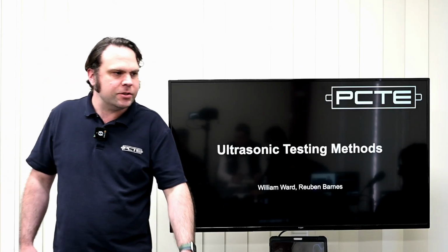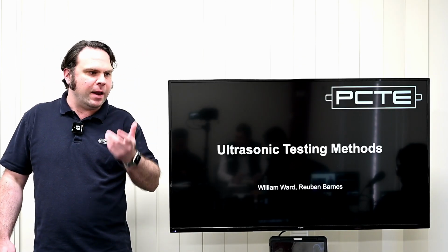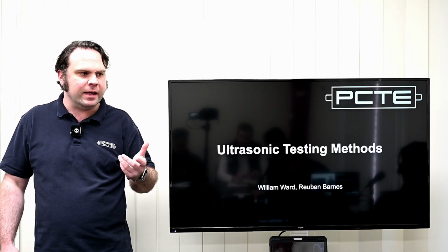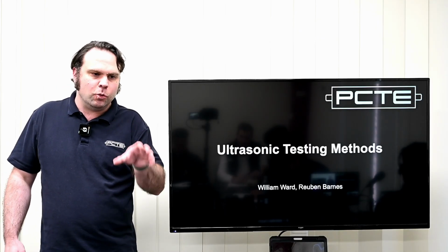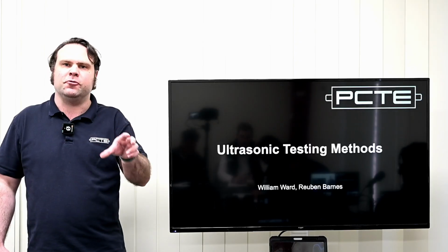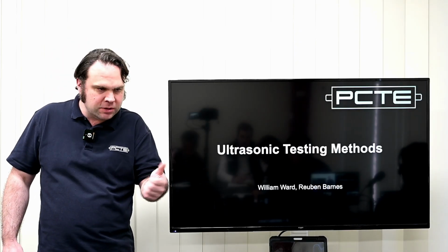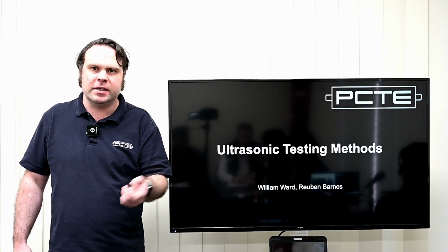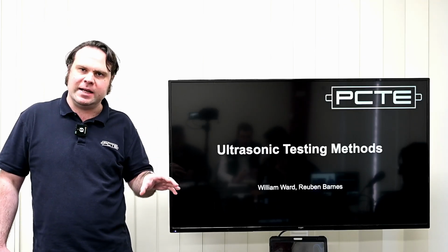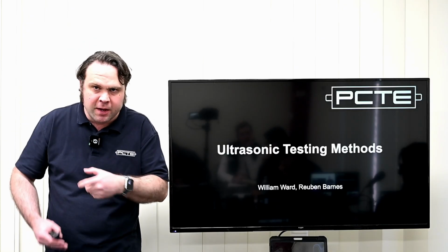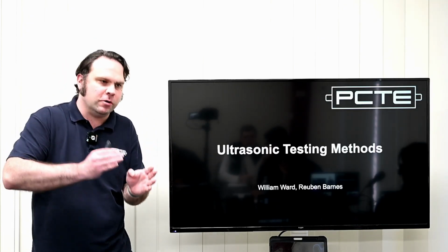This is going to be a session on ultrasonic testing methods, and we're going to be particularly looking at the ways that we can detect different defects and voids with these tools, and covering ultrasonic pulse velocity, ultrasonic pulse echo, and impact echo testing, which I sort of consider to be three tools with a lot of crossover in how they get used.